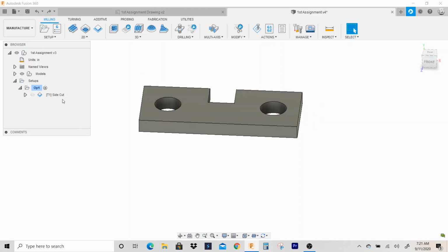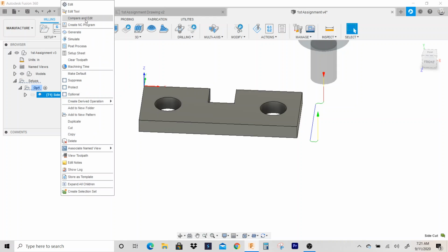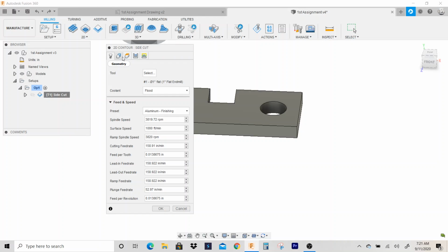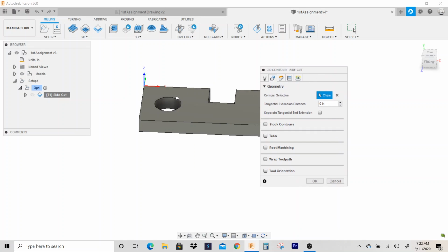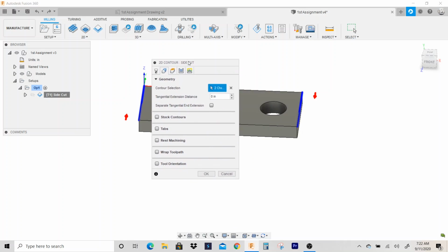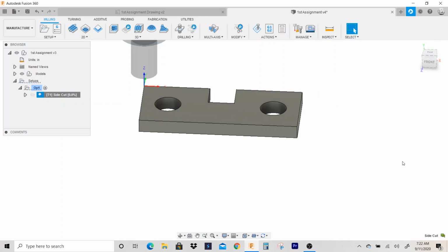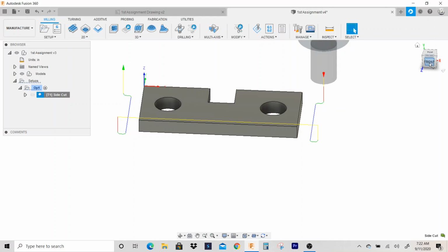I'm going to undo that. In this case, I'm actually going to go to my geometry, to my original cut, and I'm going to click also this edge, okay? Now remember, hold your Alt key down and then click on it. You can select individual lines. Alright, so I'm going to hit OK, and I'll do both of them.